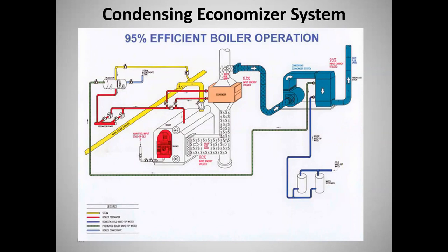Like if you're cooking tires, Bridgestone, they don't return condensate, because they have these tires and that steam comes in contact with the rubber. And if they try to condense it and bring it back, they bring back all these little bits and pieces of rubber. And those boilers don't really like having those bits of rubber in there. So it causes all kinds of fouling and issues. So they may do some heat recovery, but they don't want that condensate. They don't want that water back.